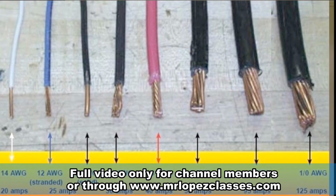I want you to keep in mind that picture. Depending on the gauge of the wire is the capacity of the wire to move amps, to move electrons. Try to keep in mind that picture. The cable 14 gauge works perfectly with a maximum of 20 amps. The cable number 12 works perfectly with a maximum of 25 amps. I want to move 95 amps. You need a cable number 2.